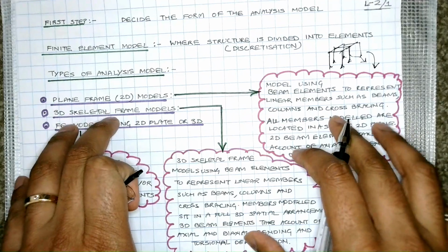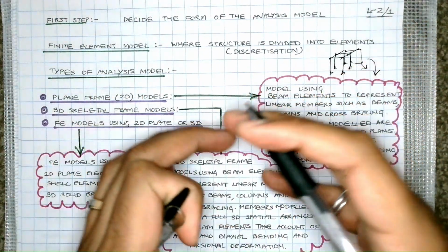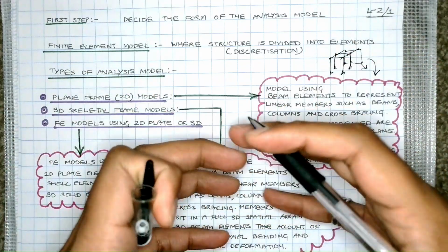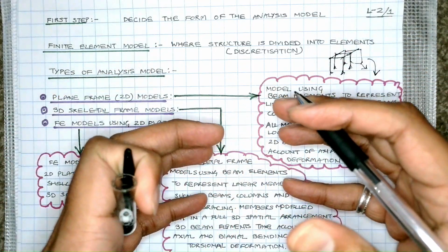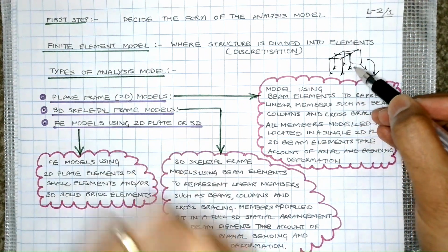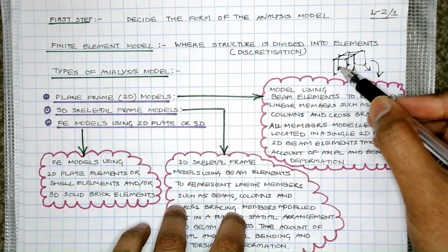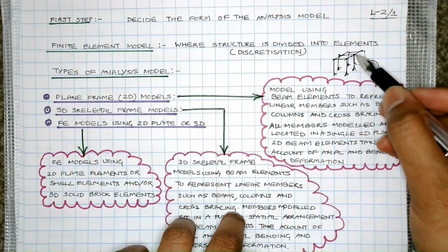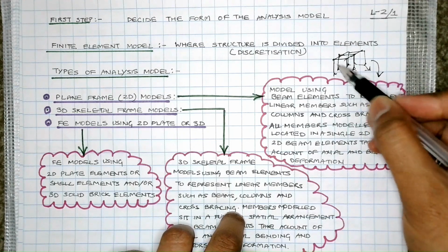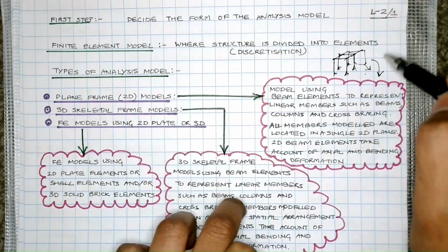What is the benefit of that? The benefit is you don't have to make your model bulky, you don't have to use many elements, your file size stays small, and it's easy to handle. You just need to focus on one frame, and you know that whatever properties you arrive at after designing it are applicable to all other frames as well.